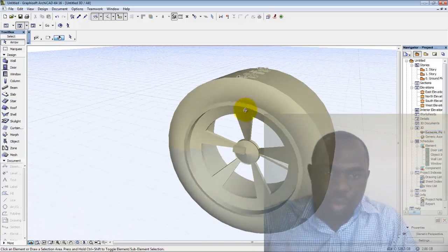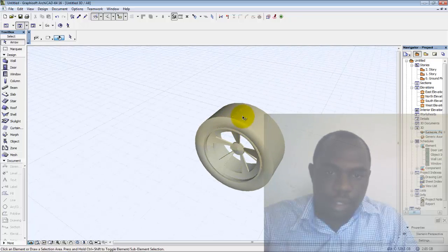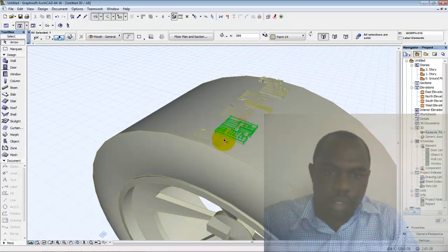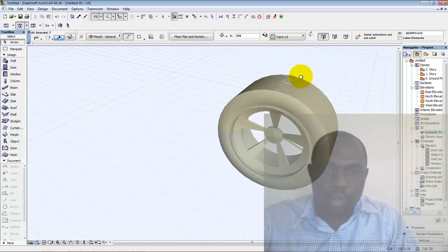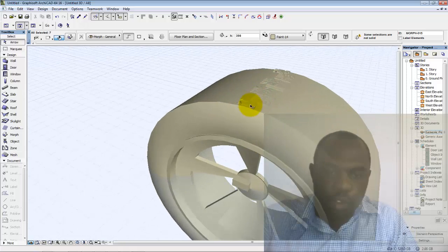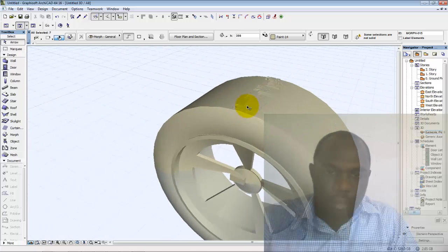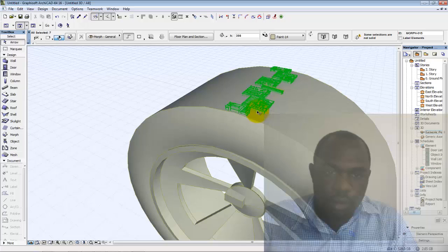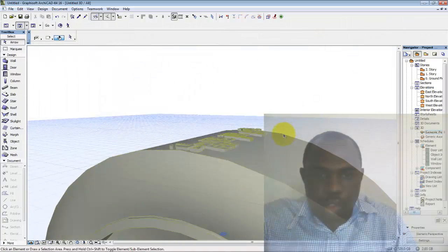So we'll go to the perspective view right now. So we're going to do the operation. We're going to select the threads and group them. Select the threads. You can just group them, Ctrl G is group. Then select the surface of one of the threads, just the surface, so that we get the option.